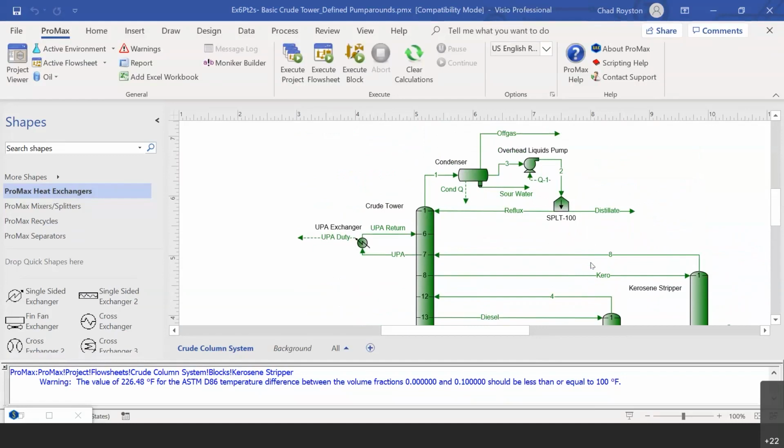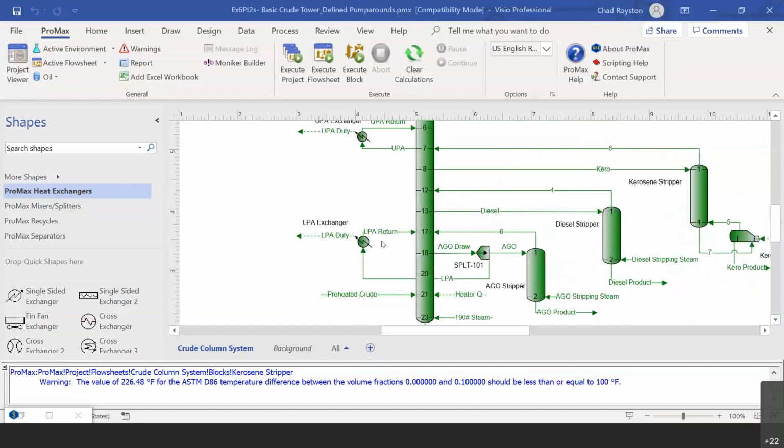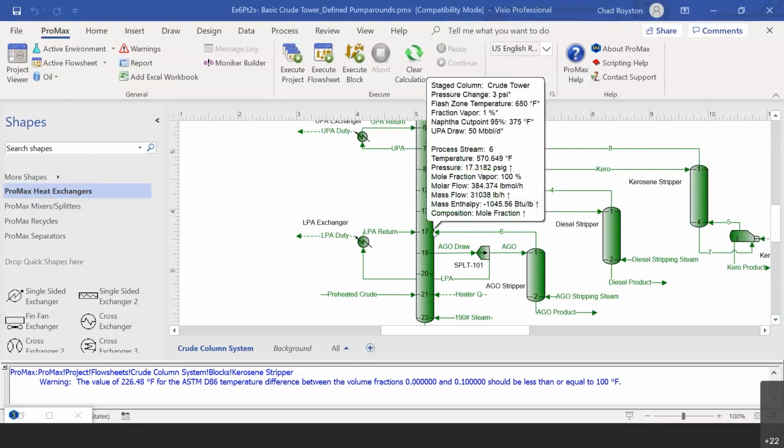Condenser duty is going to be another. Assuming you're operating the column on temperature control on your overhead, which is certainly very possible, you are going to have to create that reflux somewhere else. When you reduce your lower pump around duty, let's say your lower pump around flow rate is the same, it means you're returning liquid to stage 17 that is less subcooled and will condense less vapor in that region of the column.